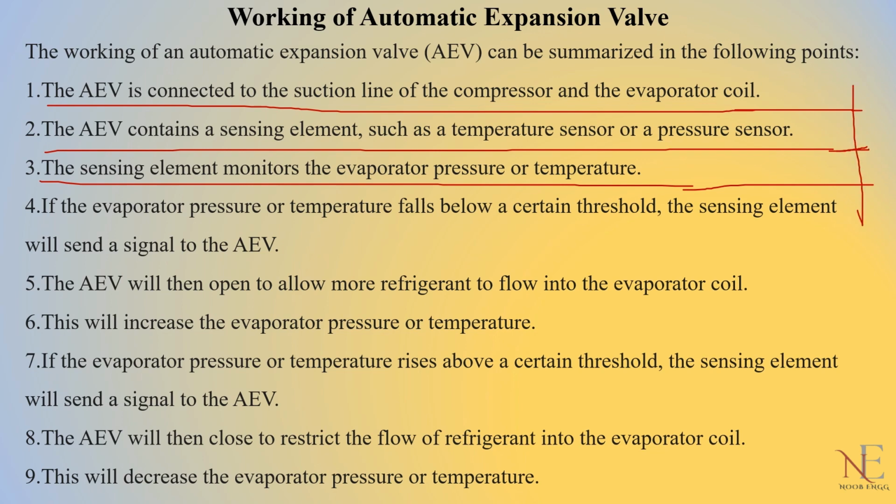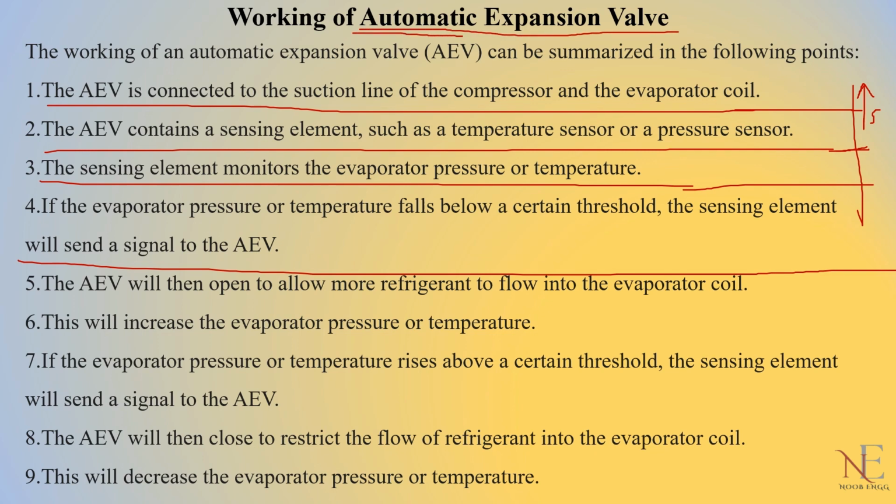As the evaporator outlet temperature increases, so that is a saturated temperature, then the expansion valve opens. This says that there is a need of liquid refrigerant. As the evaporator outlet temperature is increasing, that's why the expansion valve opens. Now you understand, for more cooling purpose.